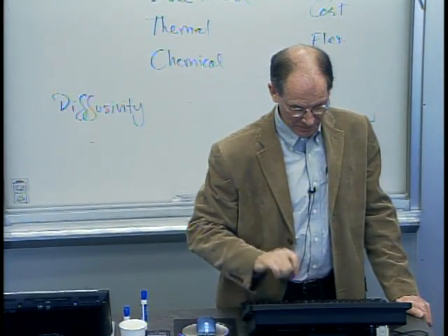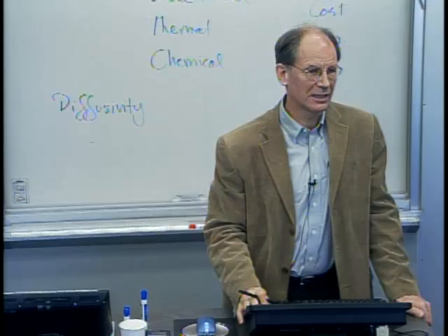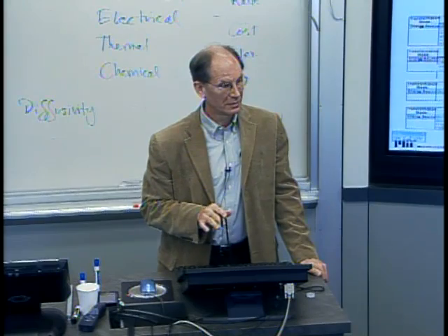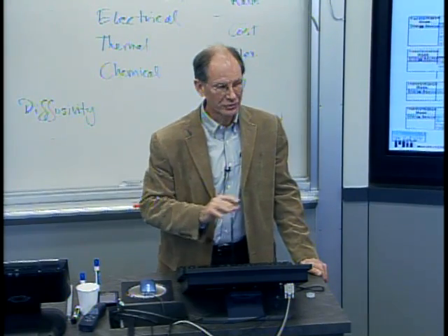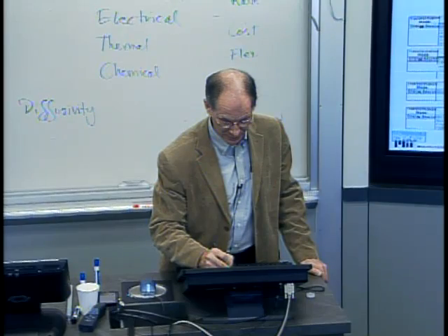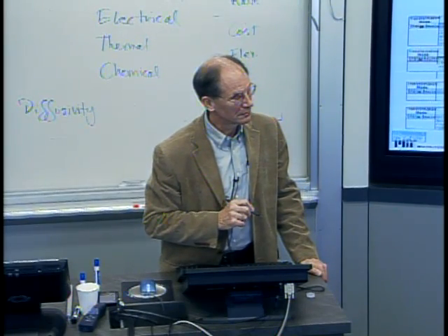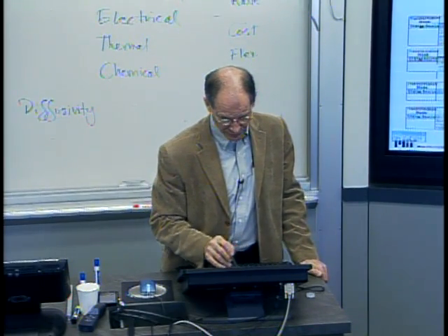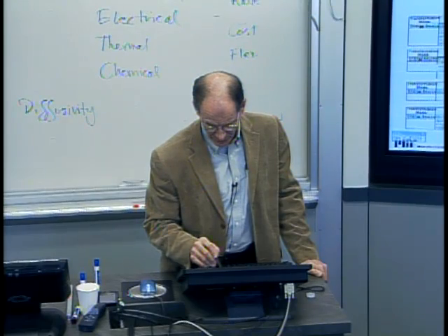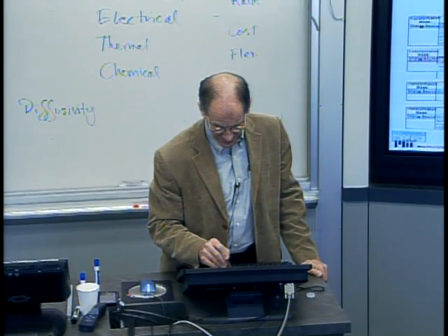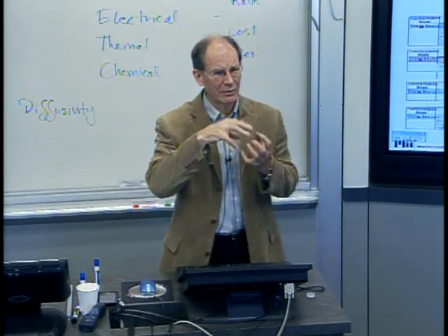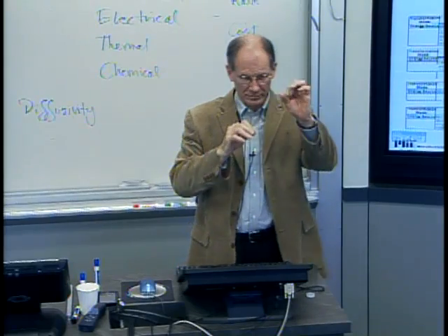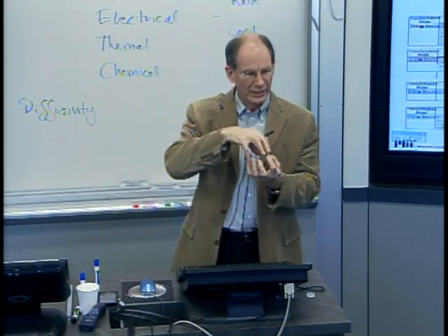Interesting. Okay. Well, that's actually an example here of where the chemical part is actually affecting properties. Not unusual. So this is still true if I'm only talking about the geometry change part of it. Yeah. There's a bunch of other ones here. One of the interesting things is if you come over here to something like hot isostatic pressing, a powder metallurgy or powder ceramic process where you take uniform powders and compress them in a mold.